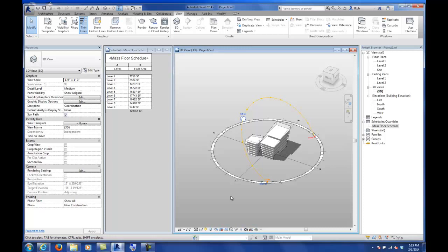The only downside to that is that when you apply any kind of floor plate or roof or wall to this mass, if you want to make an edit to that particular wall and change its design or where it's located, you have to go back to the mass and make the edits there so that it knows to change and move with the mass. Once it's hosted to the mass, it lives with it, and you have to go back to the massing element to continue to manipulate it. That is the only drawback to that method, but it gives you a lot more free-form options as well.